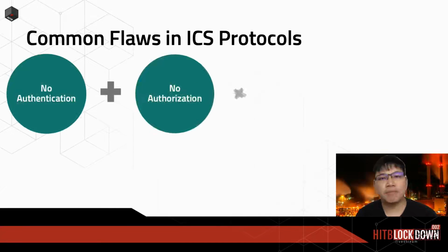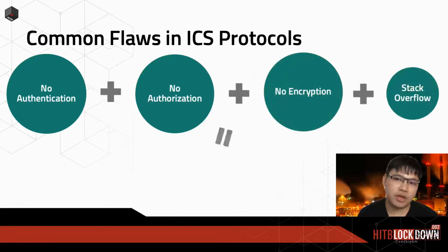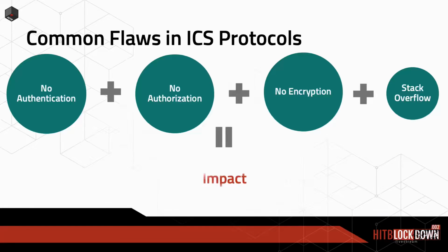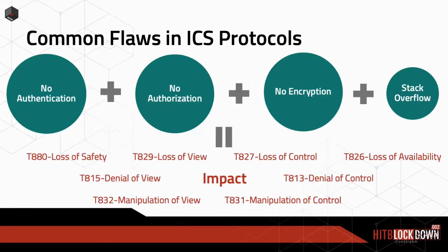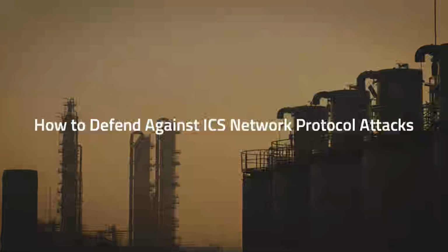So let's summarize this part. No authentication, no authorization, no encryption, and even a small stack overflow can lead to attacks. These attacks include command injection, modifying parameters, spoofing reporting messages, and command messages, and so on. Finally, we will show you how to defend against ICS network protocol attacks.